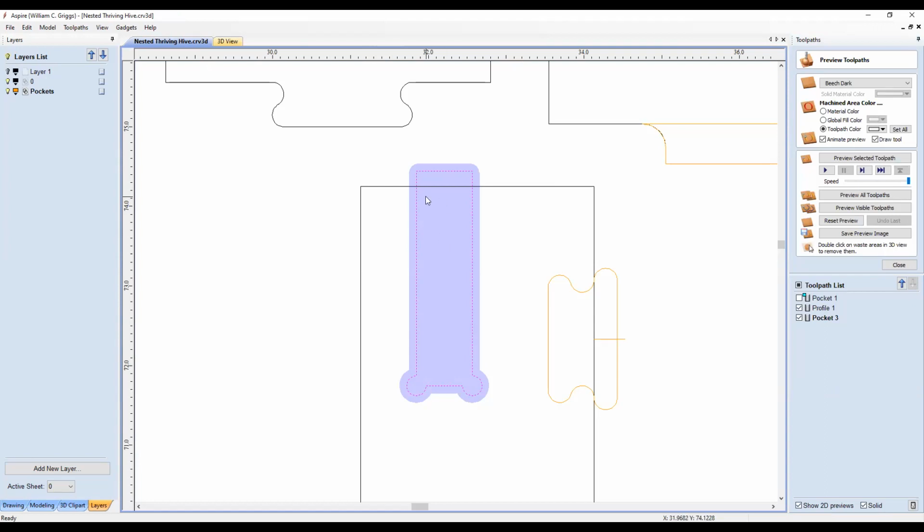Okay, which is what you would want to make the pocket fit, because if your material is 3/4 of an inch exactly, and you cut it exactly 3/4 of an inch, you'd have to put it together with a hammer. A sledgehammer. Yeah, a sledgehammer, and it wouldn't work. You have to have tolerance for the glue and for the fit, and so 3 to 6 thousandths, somewhere in that range, will probably get you through most things.